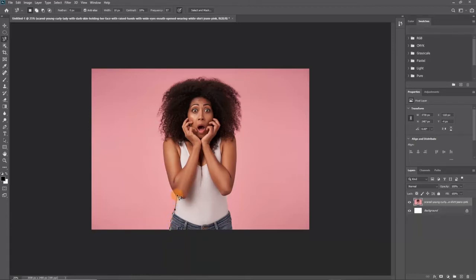What you realize is that the magnetic tool by default selects points of the image that is well defined for it to recognize, and by just moving the mouse around, it does the selection for you. So in places where the selection is very defined, if you carefully move the mouse, you realize that it just follows your selection.